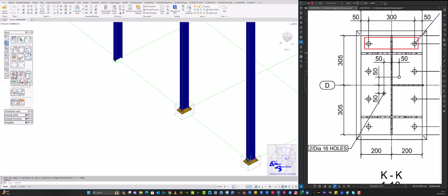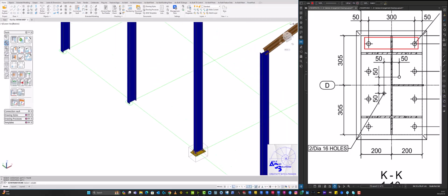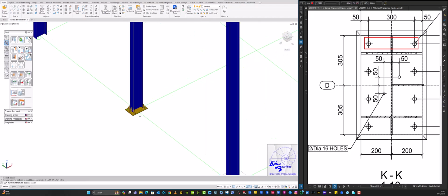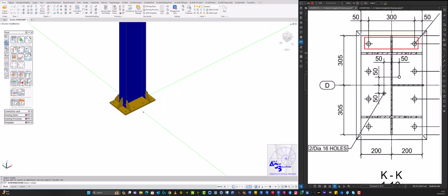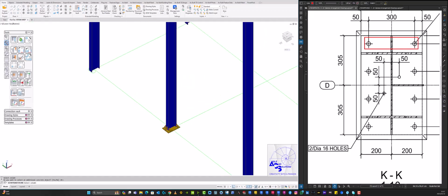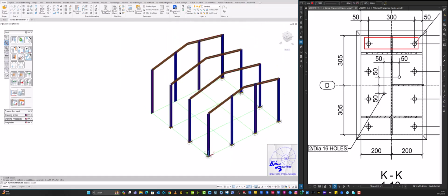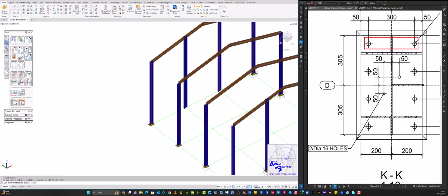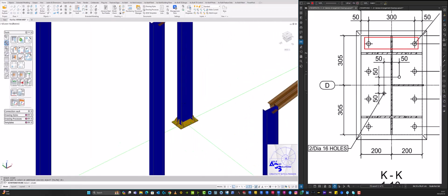If you left click on copy, select your joint box and hit enter, and then you go to the column or the position where you want it. You select the steel section and hit enter. That's how you add your base plate. That's another way of copying your base plate to all these other elements as well. So you just select all those, and there you go.